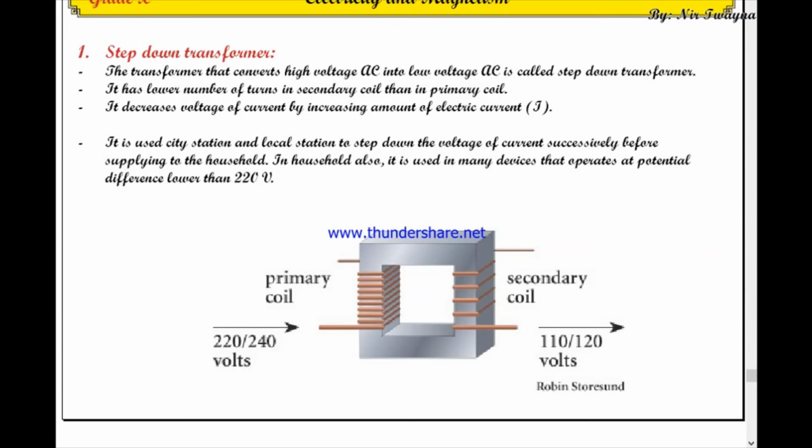Yes. Okay, it decreases voltage of current by increasing amount of current. Once again, if you supply 2.5 ampere of current at 220 volt, then it produces 5 ampere of current at 110 volt. See, as the voltage decreases, current increases. Okay, this is also just opposite of step up transformer.